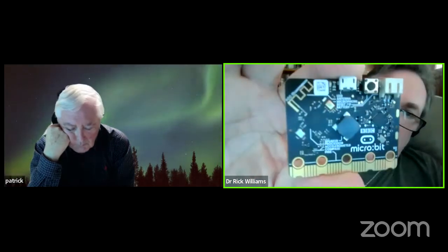We use them on all the little robotic things for tests. But the beauty of this thing is that you don't have to have hats. You can add to it. But you've got on here a BLE antenna, you've got microphones, you've got video, you've got everything, and it's very inexpensive. So we switched to this because all our other ones used to be Arduino, and we just couldn't deal with the power requirements. So we got away from it because of power mostly.